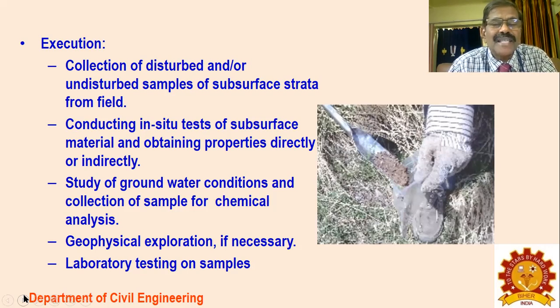Then you may have to dry it up and go for the soil sieve analysis, liquid limit, and plastic limit. Such basic tests only you can do if you have disturbed samples. So undisturbed samples are very valuable and important, because they can straight away give you certain values which are very much required for the design of the foundations. So conducting in situ tests, obtaining subsurface material properties directly or indirectly, these are some of the tests you have to do during the soil exploration execution.